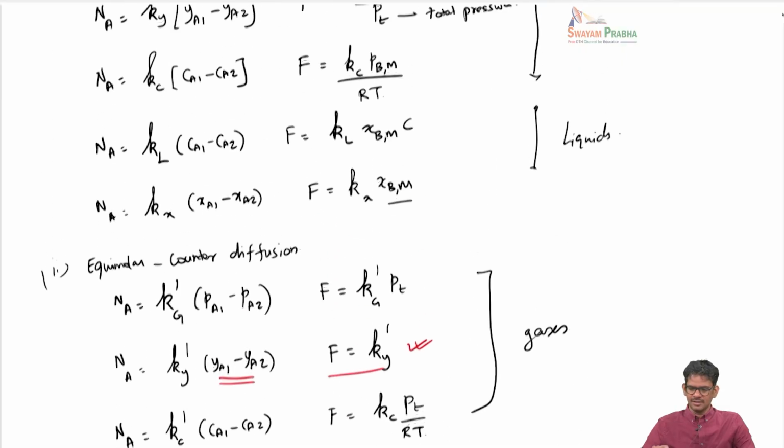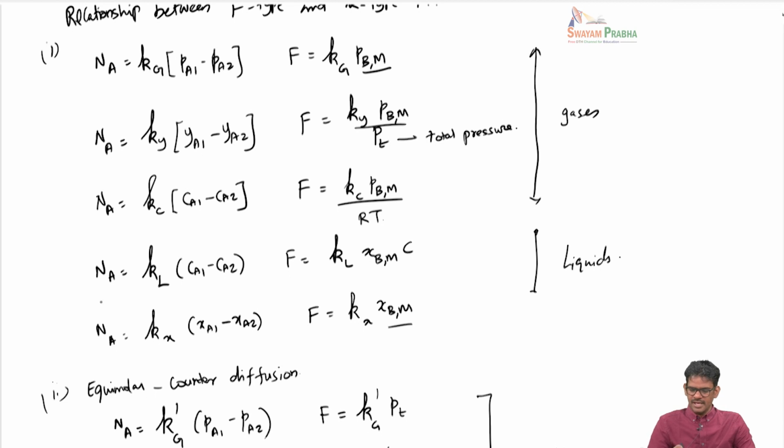And what is the driving force used in this case? Mole fraction, concentration, mole ratio, partial pressure? It's concentration. If you go back here, the way KL is defined, the expression for KL I have written there is based on some mass transfer experiment or mass transfer theory in which the flux was calculated with the molar concentration as the driving force. That's why we are using KL.